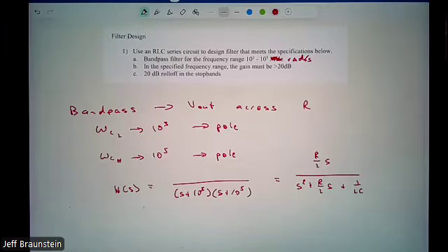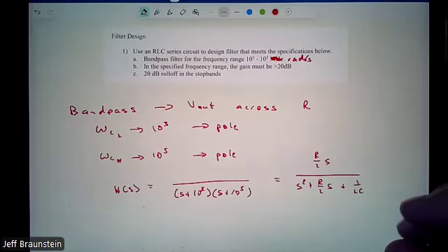Normally, I would use radians per second just to make it easier to plot. As was asked, if it was hertz, then we have to multiply everything by 2 pi, and that's going to change our numbers a bit. So just to make life a little bit easier. As we saw in the lab, LTspice, the equipment, the Scopy, everything is in hertz. So we do have to make that conversion essentially as we're looking at our equipment, but doing math, it's a little bit faster just to use radians per second. But thanks for noticing that.